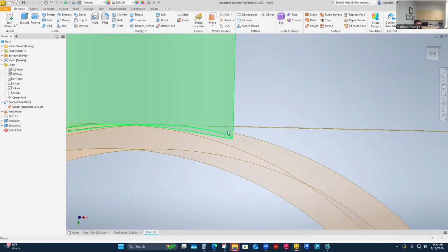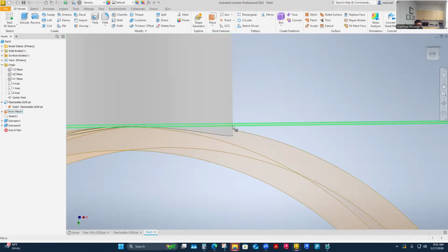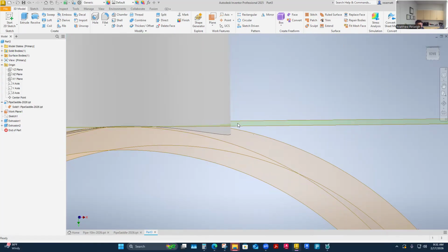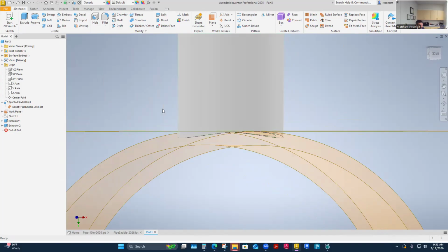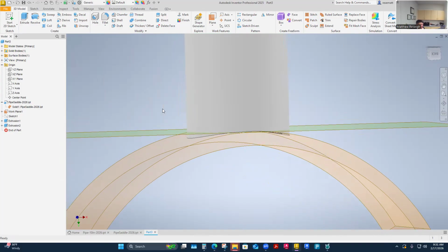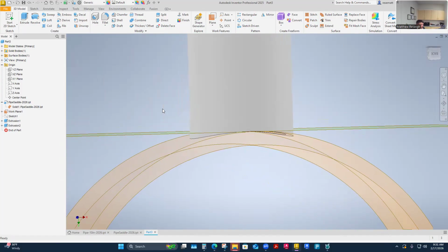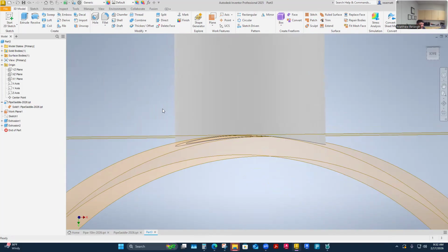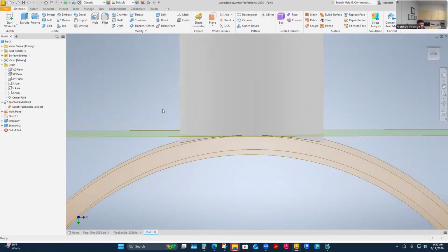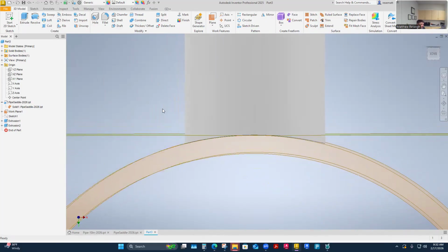But this would be really hard to make. These copes are really important because for a fitter or a welder, a square cut one would be far less workable. You'd have to fill this gap here, and it can be minimal on some parts, but it can be really extreme in other parts. And so, having these coped pipes, how do they do that? Well, Premier has a machine that you can put pipe in and it will do these kinds of cuts. It's amazing.